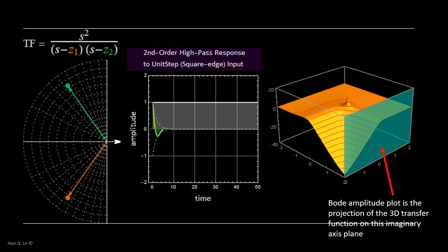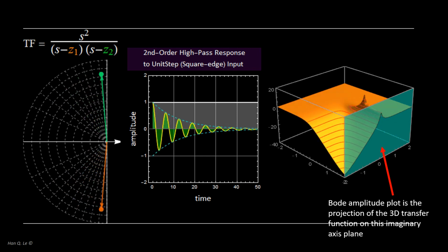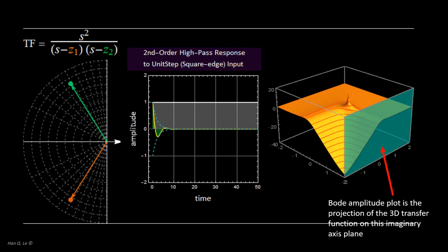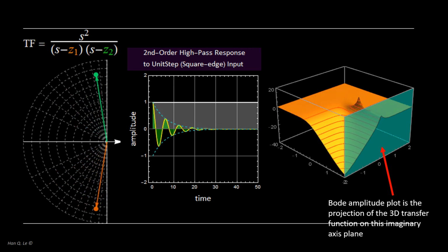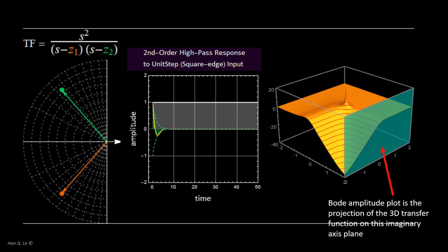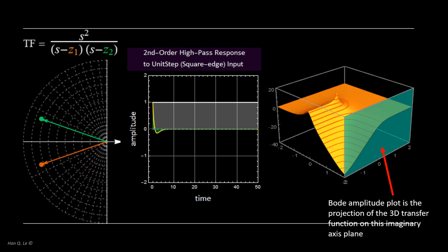Oscillatory behavior is associated with fast response. Damped behavior is associated with slow response. The balance between oscillatory behavior and fast, versus damped behavior and slow, is a matter of design choice for particular applications. In this Lab 6, it is designed for a slight oscillatory behavior in order to learn about resonance behavior.